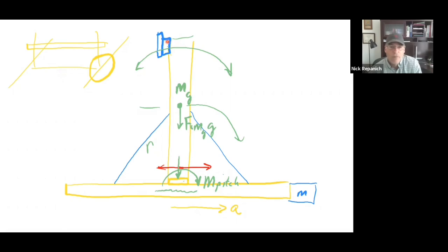This is where some machine manufacturers can solve things in programming. You could say, no, we're never going to allow this axis to move at that acceleration when the load is way up there. We'll always move the load down here, accelerate back and forth, and then allow it to go back up.